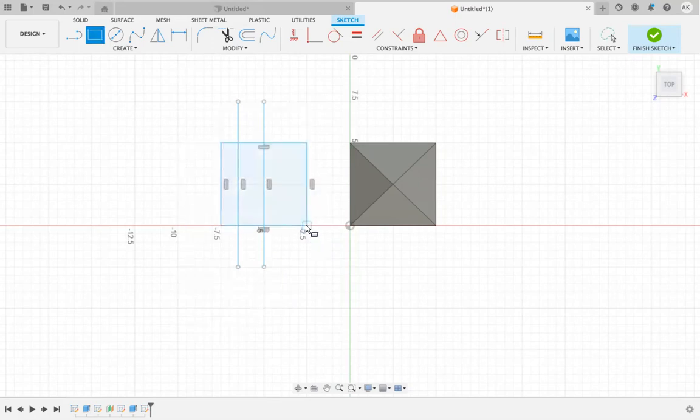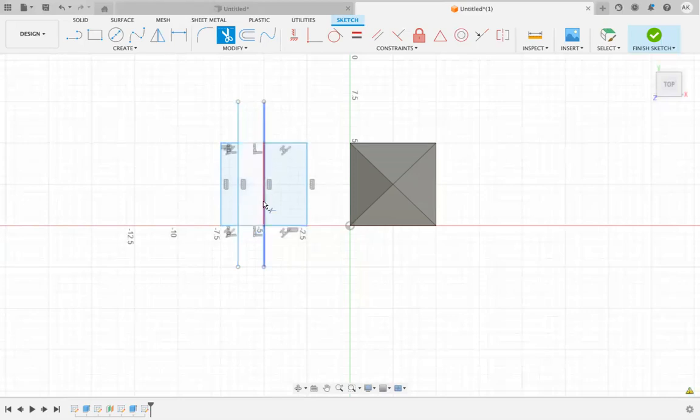Now we can trim these edges of the rectangle that fall between these lines. Look, it creates two different portions of the rectangle that are separated. So all the trim function does is remove portions of a line that have a change in surface. Usually that will just mean an intersection or a corner, for example.